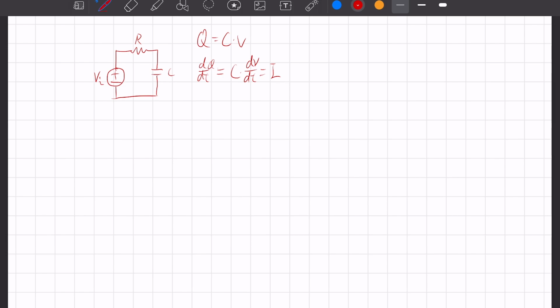Our group used a resistor and capacitor integrator to convert the output into a ramp signal waveform. First, we derive the response to the square wave using KCL, Kirchhoff's current law, to get the following formula.